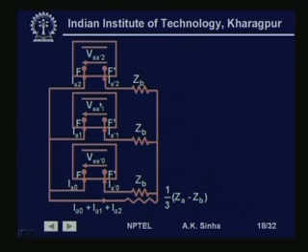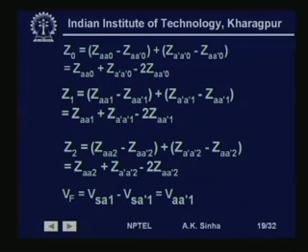Now, if we want to simulate one conductor out or a single phase open, then we can do that very easily by substituting Z A equal to infinity and Z B as finite. But before we do that, we need to compute the values of Z 0, Z 1 and Z 2 for this circuit.